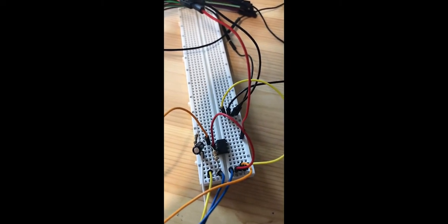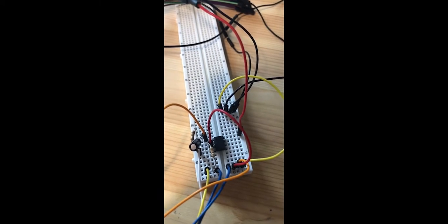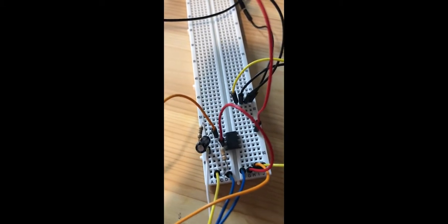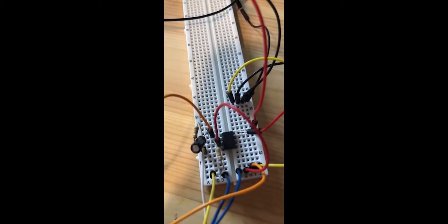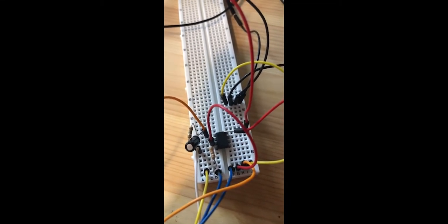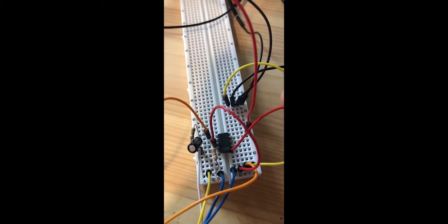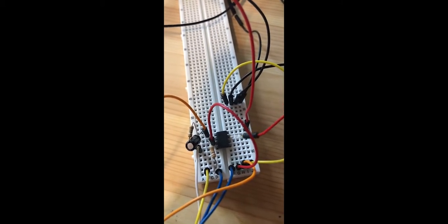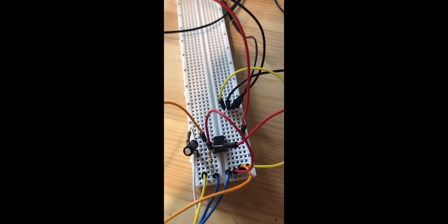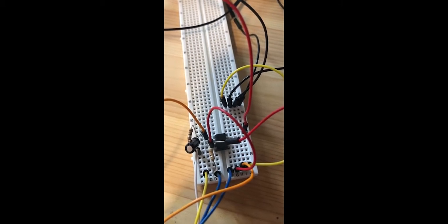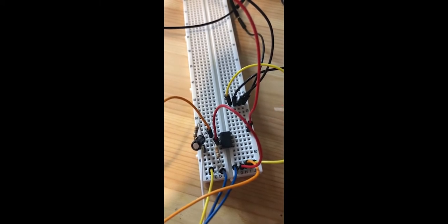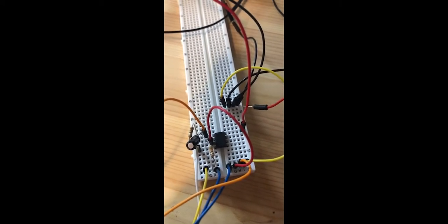This is the integrator circuit, which is in part 3.1. So again, you need to make sure that you have the supplies connection for your op-amp. This is pin 8, and pin 4. Pin 8 was positive VCC, pin 4 was negative VCC. Pin 3, according to the schematic in figure 1, needs to be grounded, and here is the connection of ground, and here is the connection of the ground, like previous